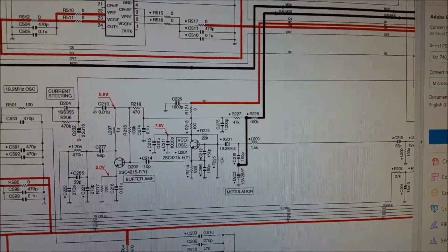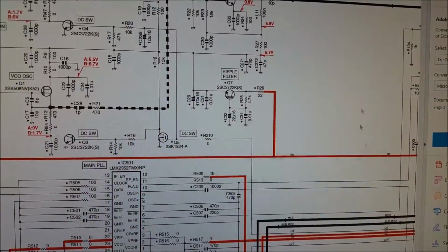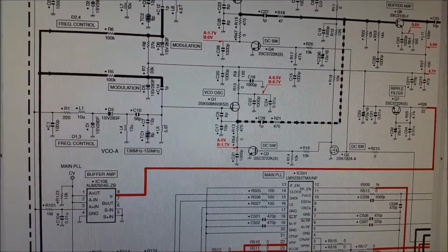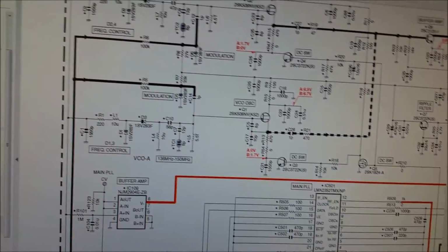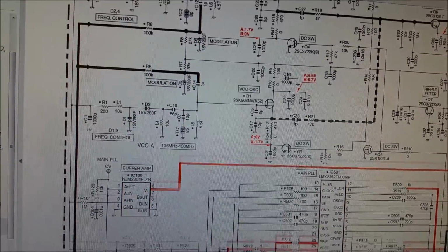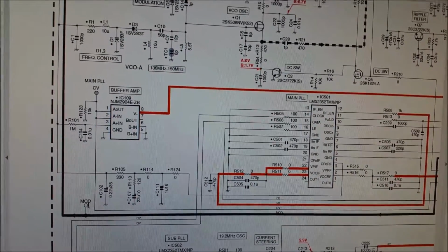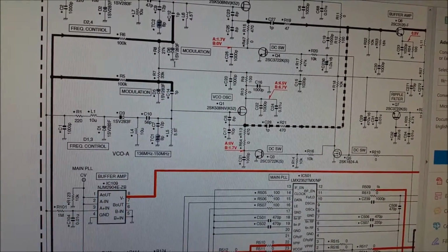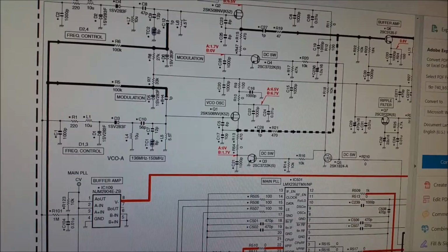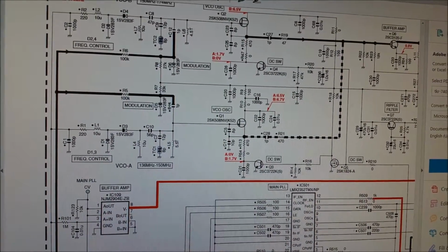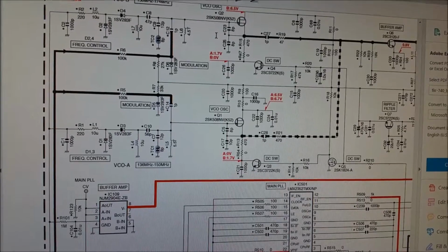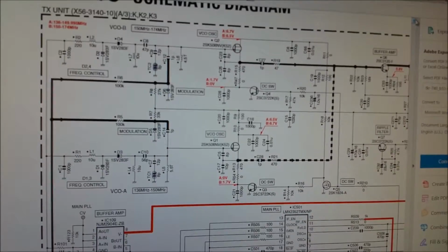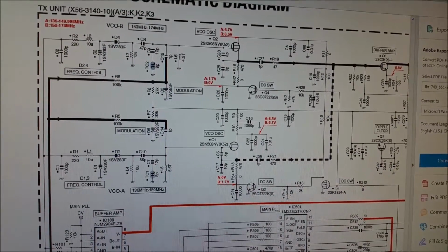Well, anyway, I noticed when I went up, I'm trying to do this around the phone, and it's interesting. Went up, and this black line here on the left is the regular modulation line that comes from the transmit audio. And there's a test point, mod, right there. And that goes directly to these varactor diodes that modulate the VCOs. And I said, I wonder what would happen if I injected a signal on those varactors. And sure enough, I am able to directly modulate.